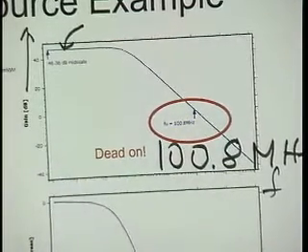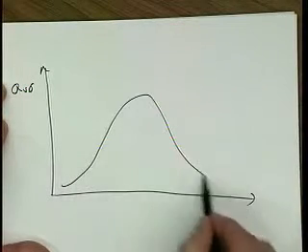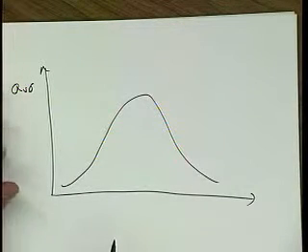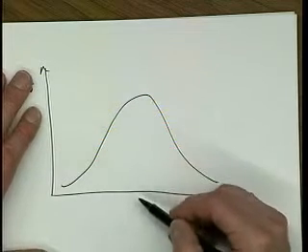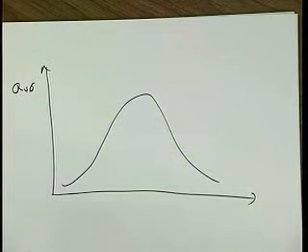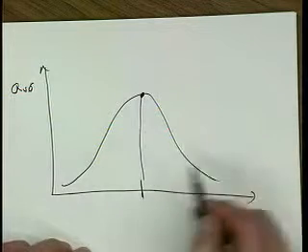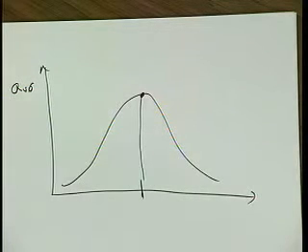No, the reason is that, remember, the AV0 of a single transistor, and hence the open loop gain of such an amplifier here, looks something like this. It depends on where we are. Well, this is not a differential amplifier. If it was a differential amplifier, usually we do the AC response of a differential amplifier for VID equals 0, and usually that corresponds to being somewhere here in the middle, and this is actually symmetrical, and we just have this peak.